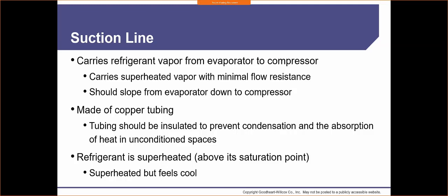Okay. Refrigerant is superheated above its saturation point. Superheated, but feels cool. Refrigerant is an interesting animal. You know, we talked about how the boiling point of 410A is -60. Well, yeah, it's going to feel cool. Even though the saturation point is, let's just say on a specific pressure, it's 60 psi, it's still going to feel cool to us because it's really operating at 30 degrees.